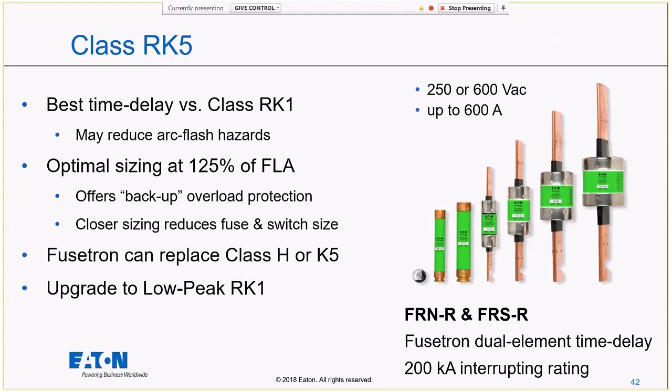It does not have to be as oversized as some other fuses, or a breaker might have to be for it. It can physically replace any Class H or K5 fuse. So Class H and K5 fuses, you'll see here, we're in the same amp ranges and the same voltage rating, but you get a much, much higher level of protection out of the RK5 fuse. So we like the RK5 fuse a lot for this reason, and it can replace those H or K5 fuses.